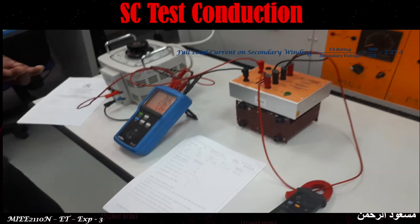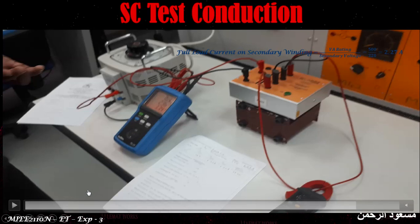That is, we can predetermine the efficiency before applying the actual physical load. That is why it is called predetermination. Without applying a direct physical load, we reach the efficiency through core loss and copper loss, because these are the two total losses in the transformer.